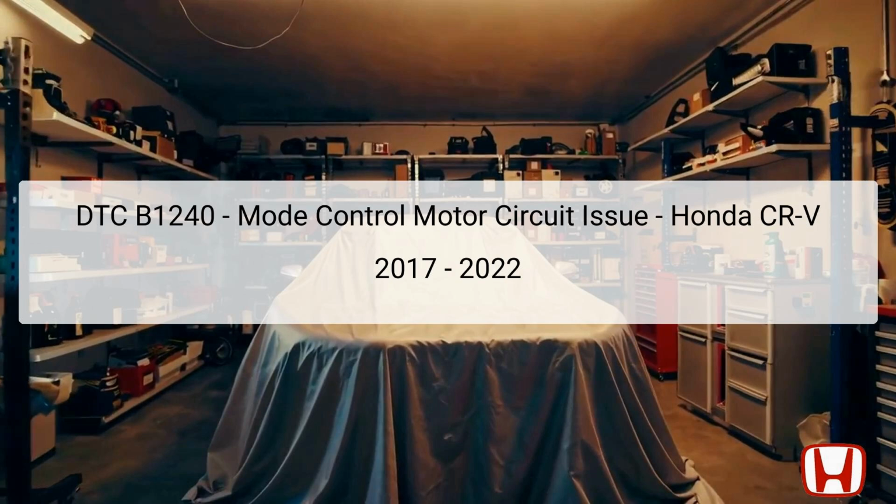This component works in conjunction with the climate control unit, which houses the controls for the air conditioning and heating functionalities. If the system detects an irregularity in the operation of the mode control motor, it triggers the DTC B1240. The location of the mode control motor is generally within the dashboard assembly, making access a bit complex due to its positioning. Proper functioning of this circuit is vital for maintaining passenger comfort, as it directly influences air distribution and flow inside the vehicle.